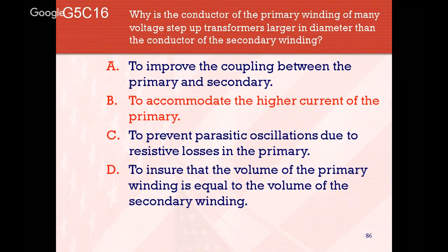So if it's a step up transformer, you're going to have a lower voltage, higher current on the primary, and thus you need a heavier, larger diameter conductor.